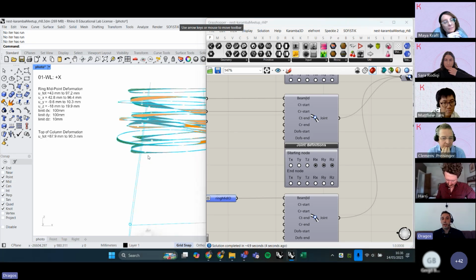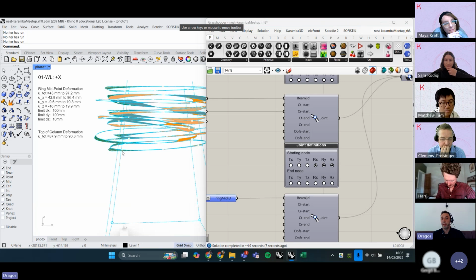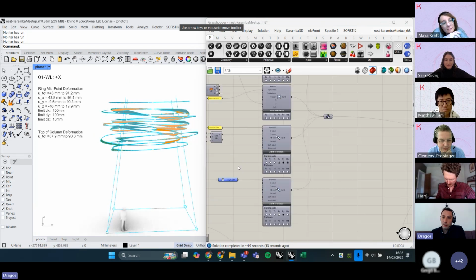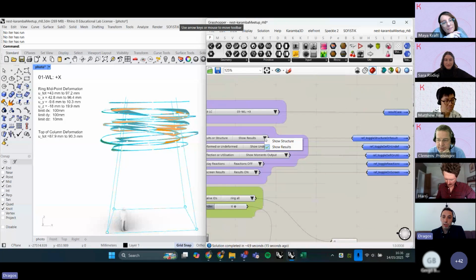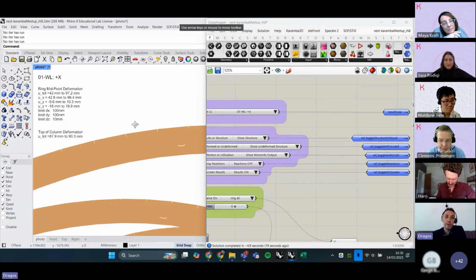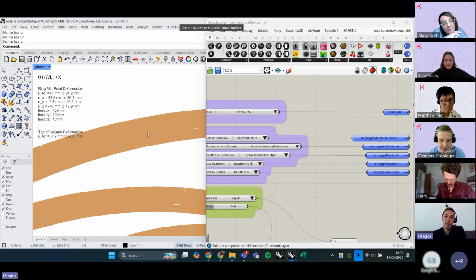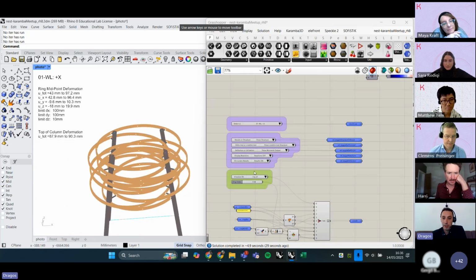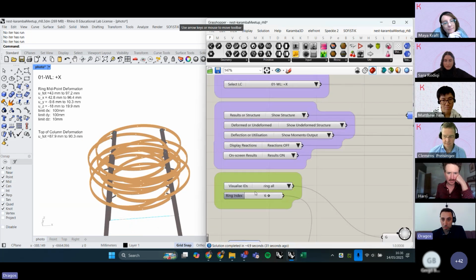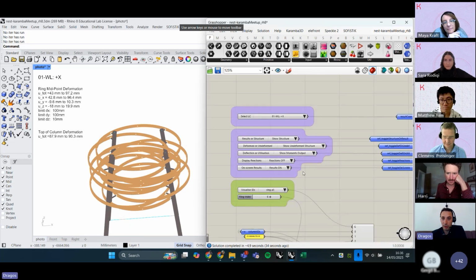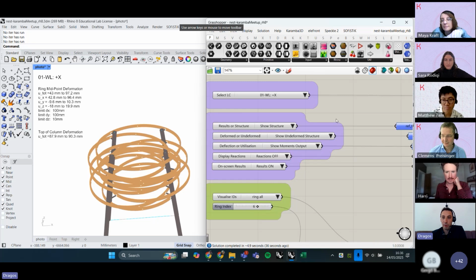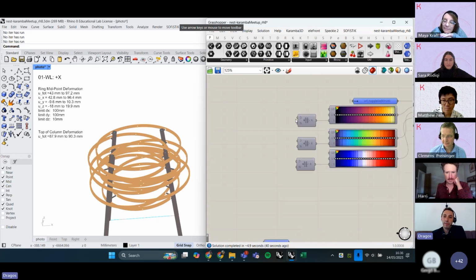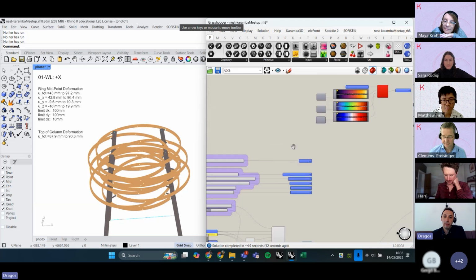So that essentially tells us how to design this connection and how to keep the member at this size. Maybe it's worth mentioning the members are 91 millimeters wide and 200 deep. So that's really, really small to try and put any moment through that. I think that's all I wanted to show on the live demo. Yeah, I think the different gradients are useful.